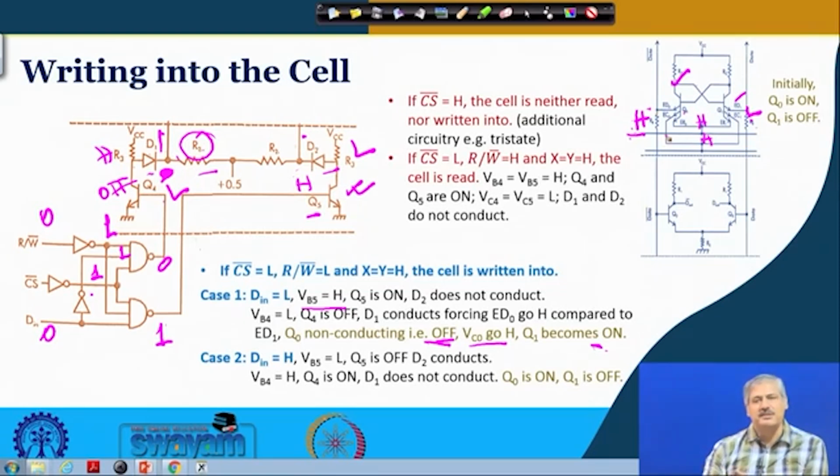Right. That is how the switching is taking place within the memory cell, where the transistors are changing their on or off value. If Q0 on was logic 1 stored, binary value 1 stored, then Q0 off is binary value 0 stored, the way we have seen before, and if we now do the reading, we will see that 0 was there. So, 0 will be read now at the D out over here after this operation. Okay.